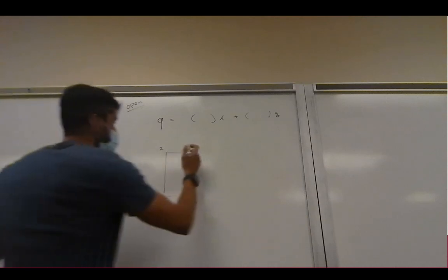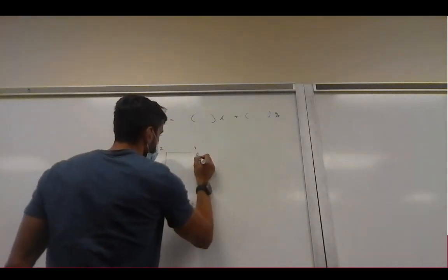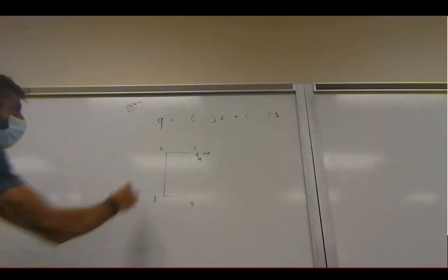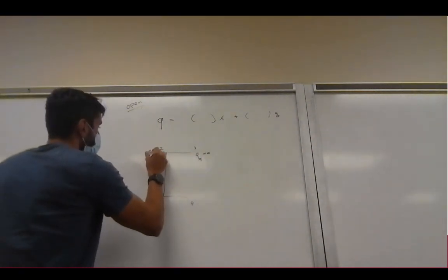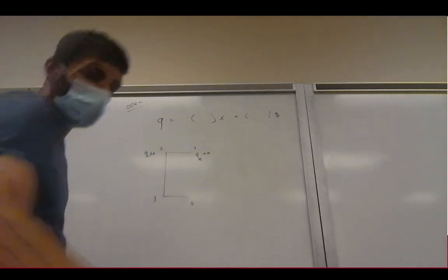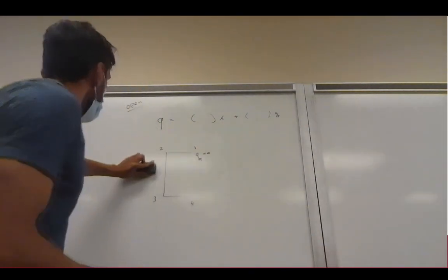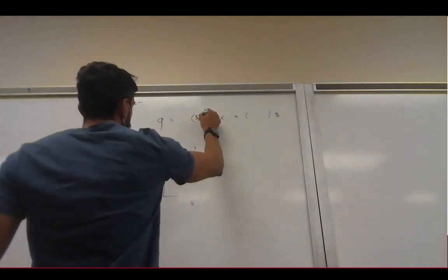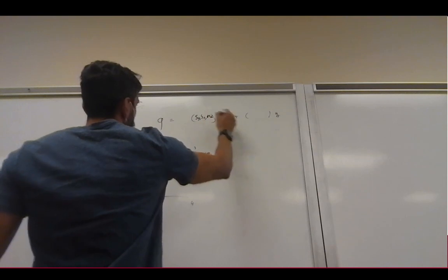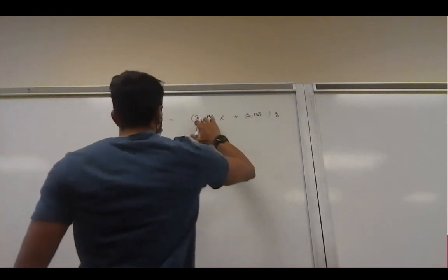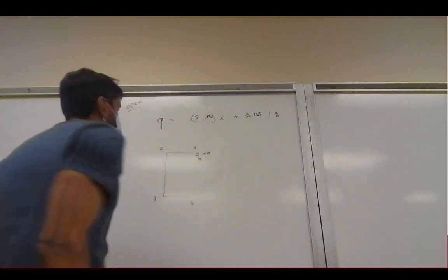And the reason is that we know that at the start point 1, q1 is equal to 0. So we know our starting point. At 2, q2 is not equal to 0, so we don't know it. We have to calculate that first, so we cannot start at that point. And this is of course a function of Sy, Sx, the shear forces, and the moments of inertia.